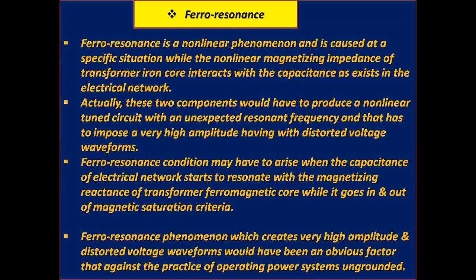Now I have to discuss the topic of ferro-resonance. What is ferro-resonance? Ferro-resonance is a nonlinear phenomenon caused in a specific situation when the nonlinear magnetizing impedance of the transformer iron core interacts with the capacitance that exists in the electrical network. Actually, these two components produce a nonlinear tuned circuit with an unexpected resonant frequency, and that imposes very high amplitude, distorted voltage waveforms.